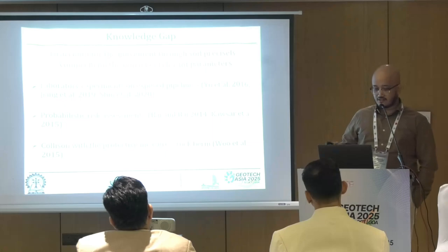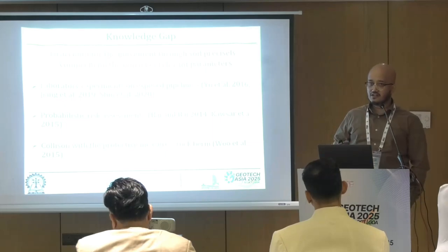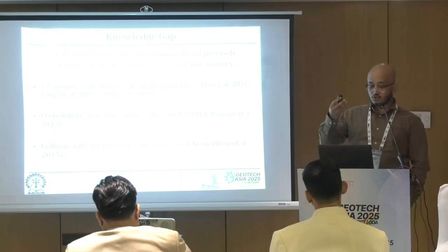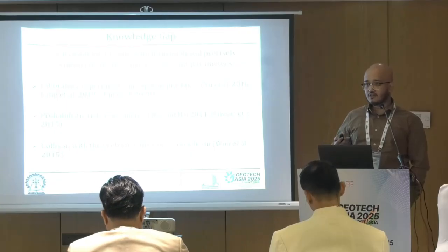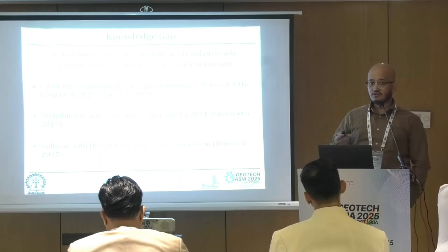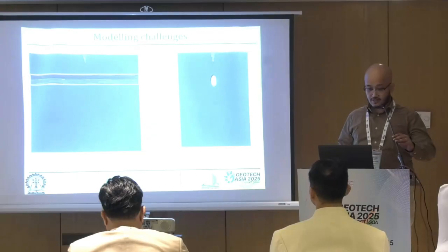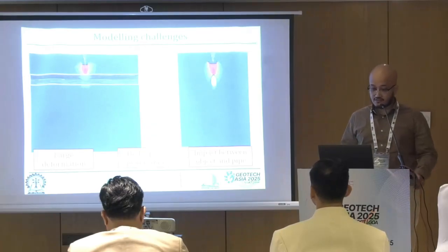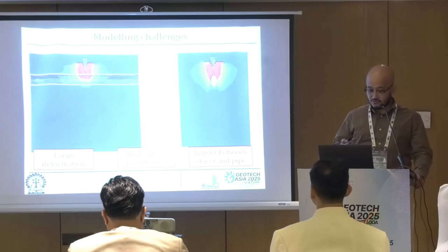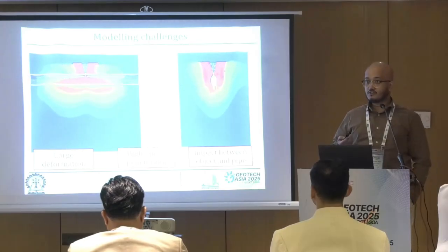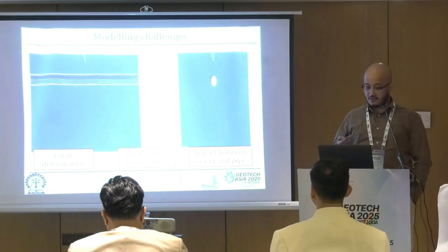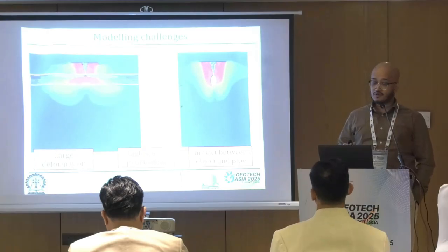In that situation, the major difficulty is to track the movement of the object through the soil, simulate the impact it will cause with the pipe, and obviously understand the impact of different parameters on this study. As this is a very fast penetration problem, the major challenge is to track the movement of the object through soils as it hits the pipe and creates a dent in the pipe itself. It's a large deformation problem numerically to solve.